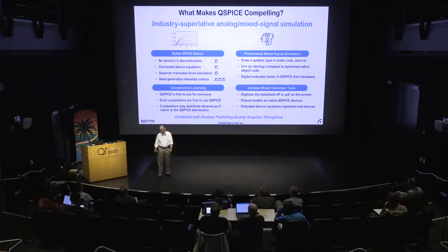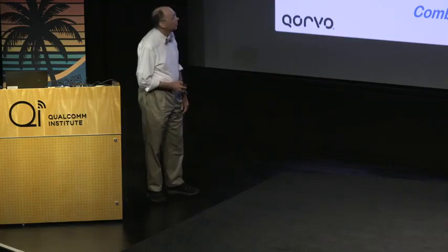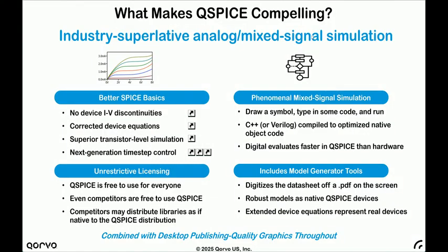It's almost technology. I don't like to use the word technology unless you have lithography and ions and bakes and things, so I don't like to call software technology. But this is almost technology. It's a big thing. It uses the open source Verilator to convert digital Verilog into C++, and then it compiles it with the Digital Mars compiler, the free compiler. All that's included. You just install QSPICE, those compilers are included, type in what you want, and it just works.